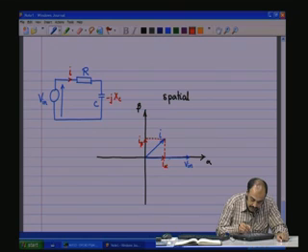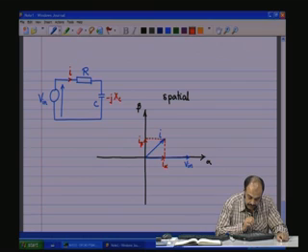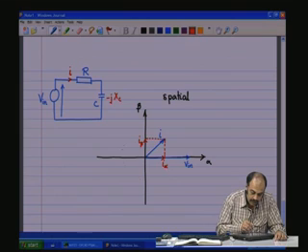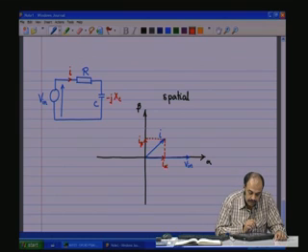So, I alpha into R is the voltage portion which is going to be in phase like that, and I beta is due to the capacitive reactance, and this is the resultant current due to the in phase component of the current and the out of phase component of the current. So, this is how the vector diagram would look like for an RC circuit.